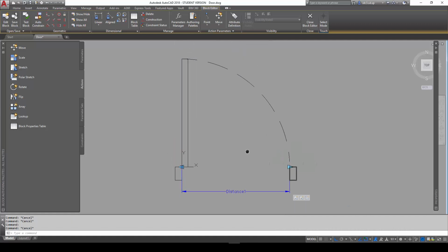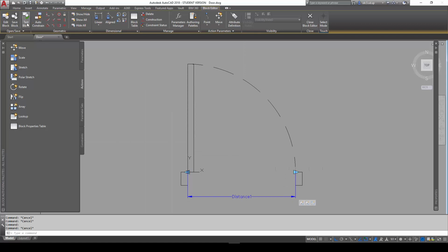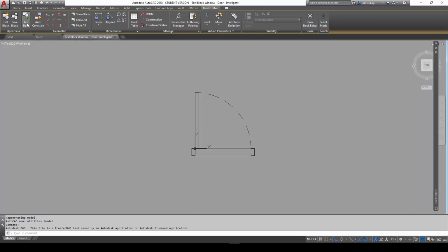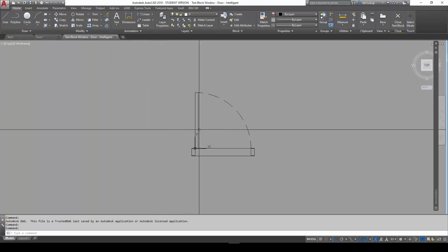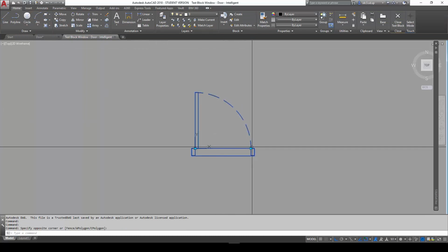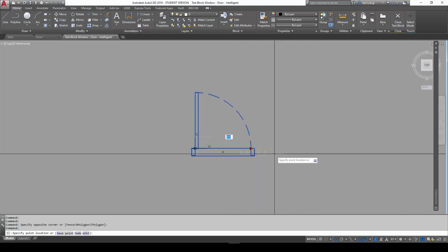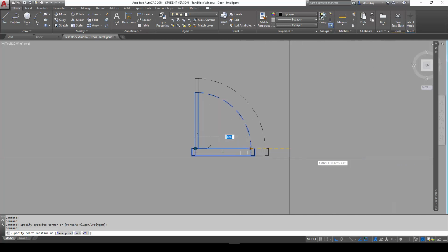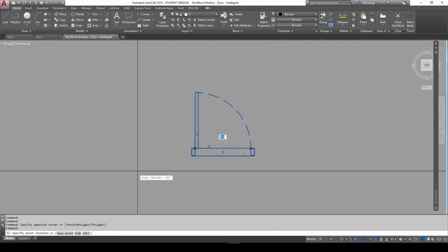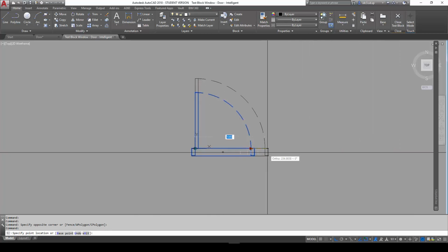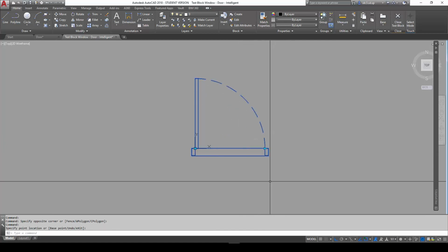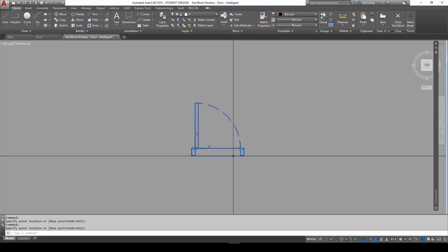So we are going to go in again, lastly, to test the block again to just make sure it can work properly here. So we're just going to select this again. And if you notice, it now constricts us from stretching it way too far out, too big or too small. So it is always going to fall within that prescribed size. For example, it's set to maximum at 1 meter, so this door has a clearance of 1 meter now, or it has been set to the smaller size at 650.